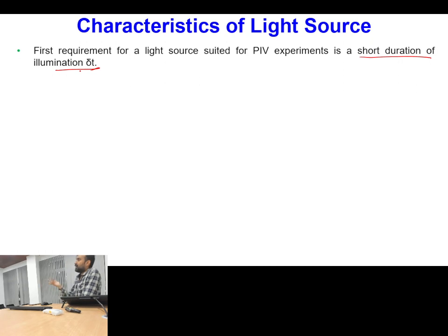Typically, in PIV there are two different types of setups: low frequency PIV measurement and time resolved PIV measurement. The low frequency PIV setup is typically used for steady velocity measurements, where we are not much interested in a huge number of pulses.